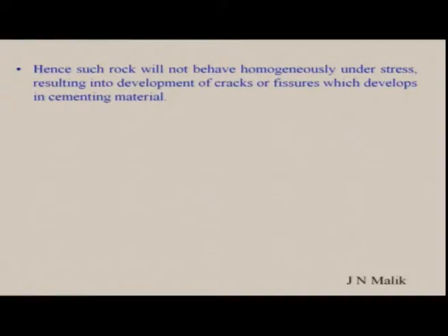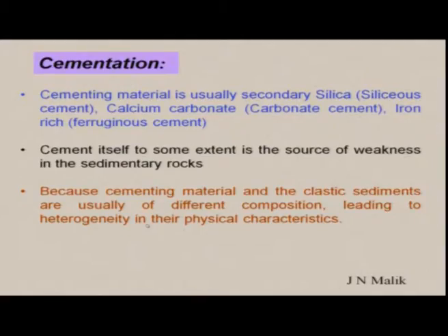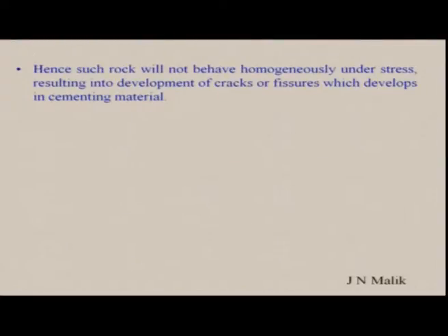So because of this, such rocks will not behave homogeneously under stress. Okay, so this is a very important part when we talk about shear strength and all that. Since they are comprised of different materials, we will have a sort of heterogeneity of the material within that clastic rock. Hence, they will behave differently under the stress, resulting in the development of cracks and fissures.